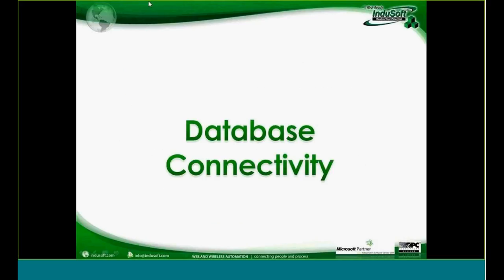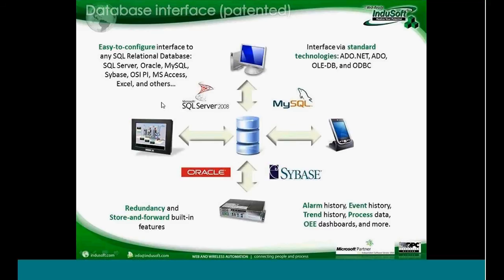So let's talk briefly about the database connectivity that we have. Built into InduSoft Web Studio, we can connect to just about any SQL relational database. In fact, if it's SQL related, we can probably talk to it. So there's Microsoft SQL Server, there's Oracle, Sybase, MySQL. We can even talk to historians by other vendors, including something like OSI Pi as a historian. We can even work with Microsoft Access or Excel and treat those as databases and interact with them as databases. For example, Excel is not a database, but we can treat it like one and interact and work with it.